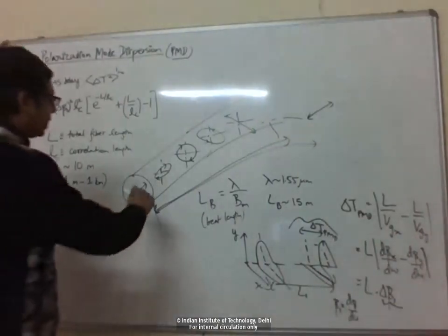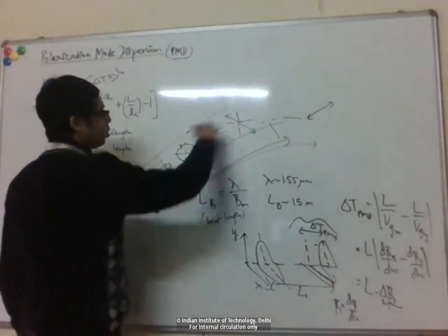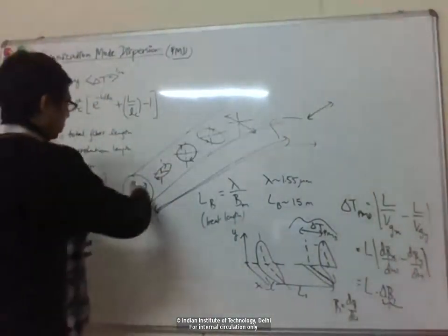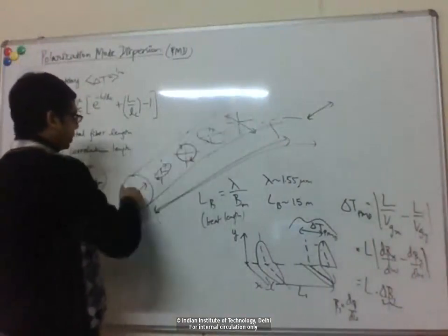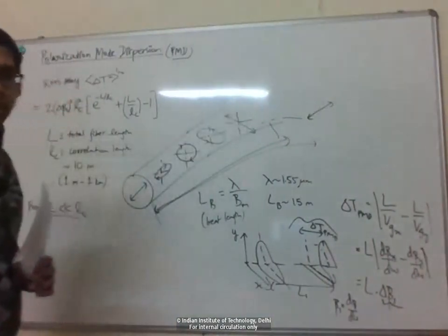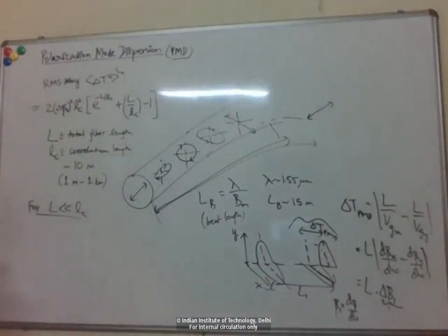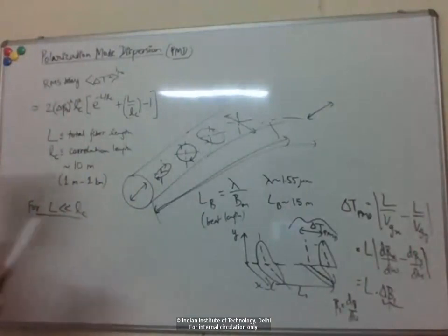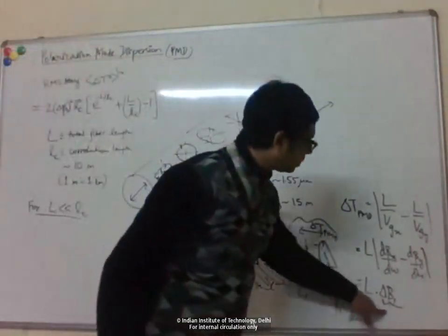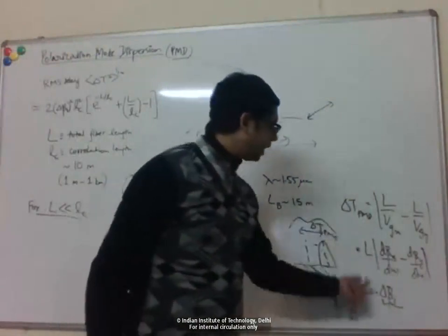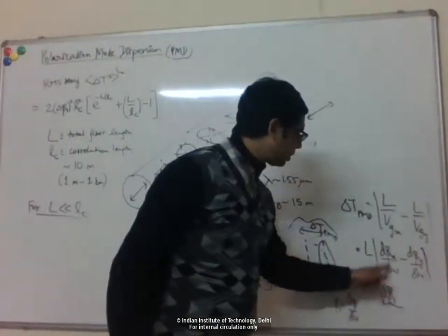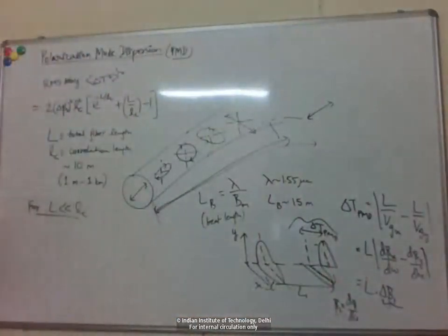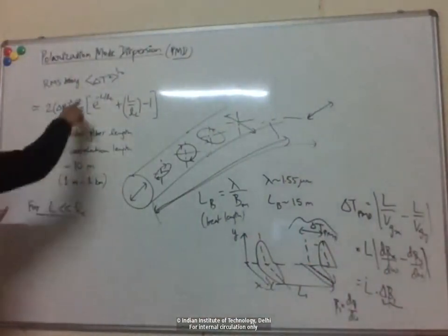It's basically like a uniform fiber with uniform birefringence, a short piece of fiber with no change in its properties. So delta beta is just a constant over that fiber length, and we should get back the earlier expression: the broadening should just be the length times the difference in group velocities. We can check if that happens.